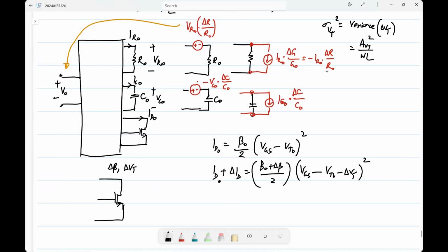Okay. So just from this expression, you can see that you can combine these, right? VGS minus delta VT, and have this delta VT over there. Okay. So then whatever voltage is applied here, which is the actual VGS, will appear as VGS minus delta VT to this ideal transistor. Okay.